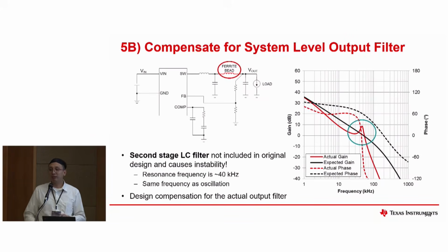Actually, I do have experience with some customers where they tried to follow the EVM design, but when they looked at the output, they added some additional filtering because they thought they needed it. Yes, you should resimulate again with the values. You definitely have to consider, as mentioned, designing the compensation for the actual output filter that you're using, out of the box.